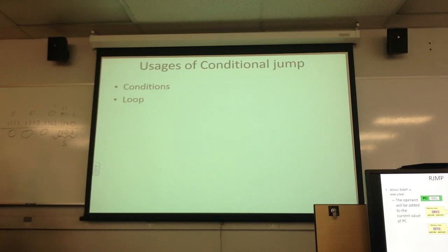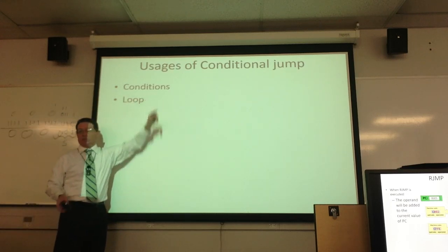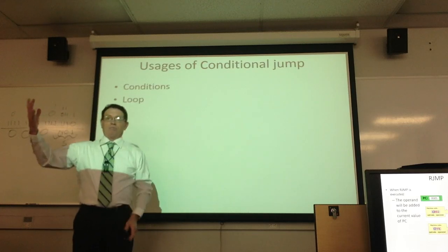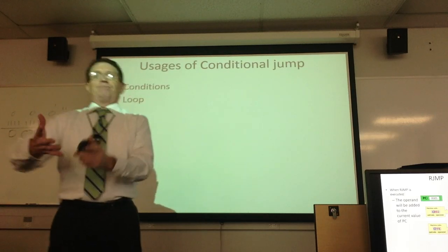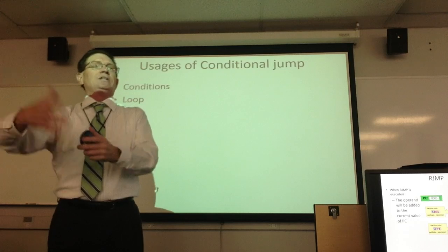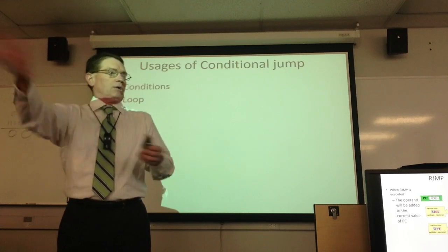The idea for this is to do two things. You can set up conditions on which I want to loop. So I'm testing something. I could be grabbing bits in off an I/O port, testing them, and then that could give me some kind of condition to jump to. Say port D is tied to 8 windows or 8 doors on a floor in a building.